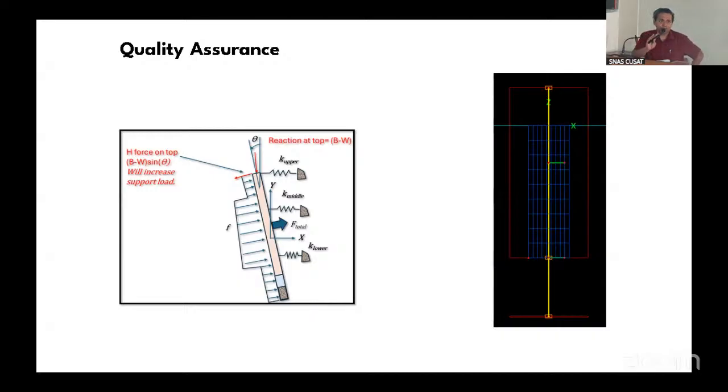So every time you get a problem, instead of jumping into the finite element, you need to understand the boundary value problem. You need to understand what the forces are. Try to make a simple stick model, or a plate, a very simple drawing, and try to figure out what the forces are, how the body is going to move. I mean, what is really going to happen out there? Really understand the boundary value problem before you do your FE analysis.